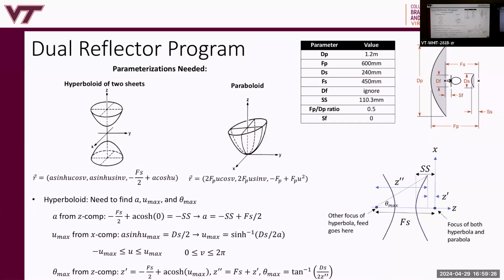So it's because everything is based on localization. We model everything in ray-based theories as we only need to trace a piece of the wavefront at a time, which means other parts of the structure, the current induced on them, don't affect what's happening locally at the point of intersection of a ray and the geometry. So we can consider one ray carrying one piece of wavefront, and reflection problems using canonical geometries that represent locally what that geometry looks like, half plane or infinite sheet, at that point of reflection. Now that's valid for electrically large structures, right? You know, tens, twenties, or hundreds of wavelengths. The bigger it is, the more accurate it is.